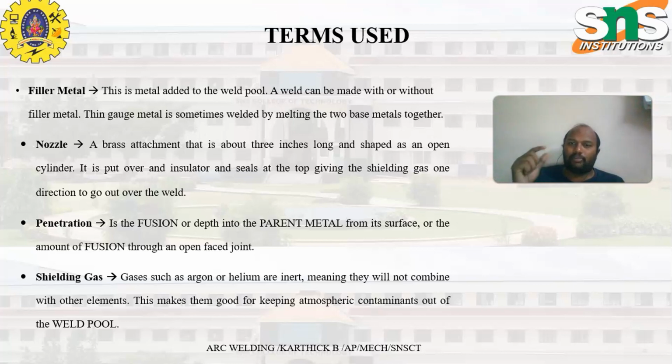In other words, for example, if you have a mild steel plate for butt welding, you are going to use a mild steel electrode and the SMAW welding process to make the weld over it.